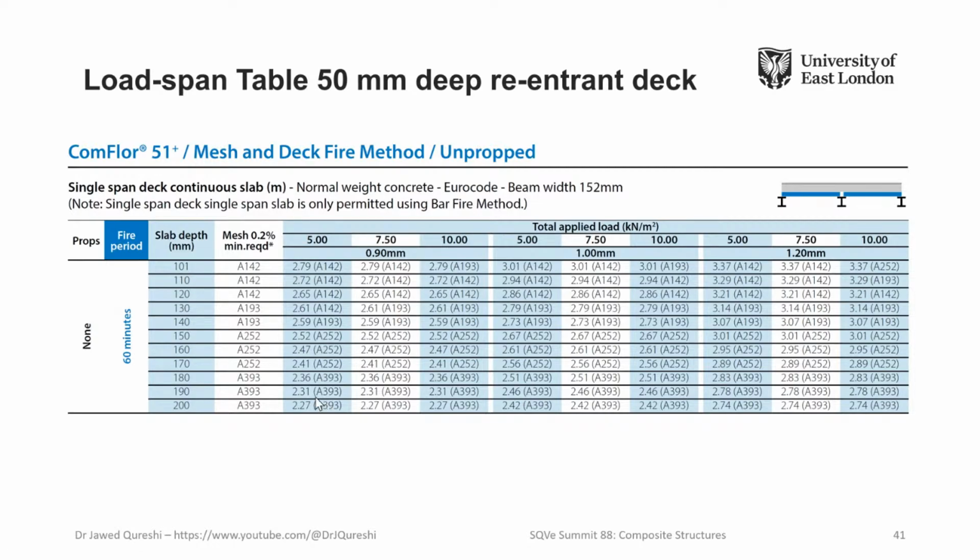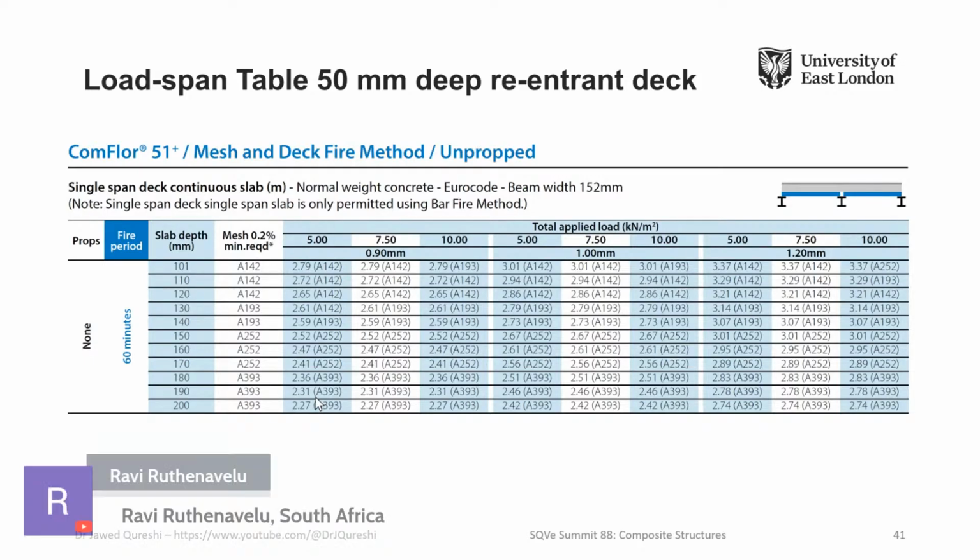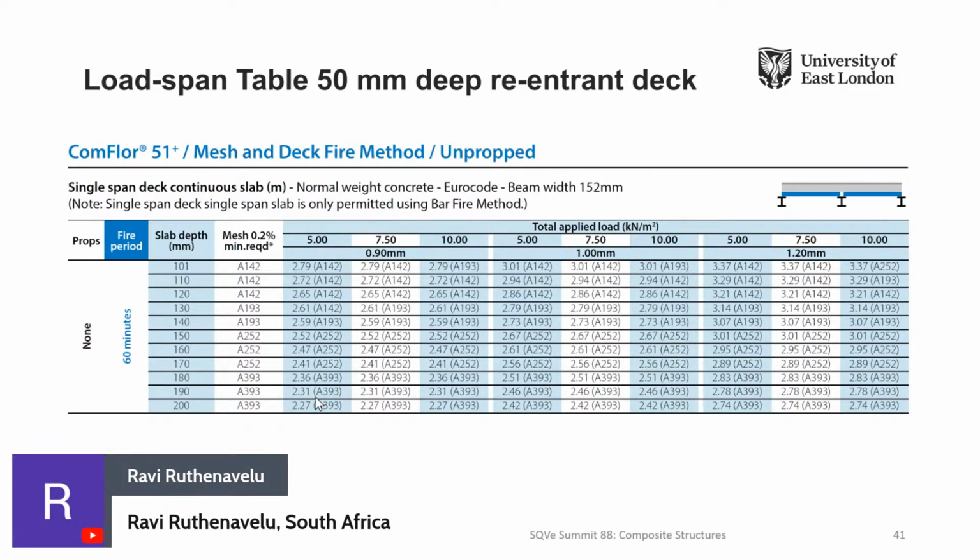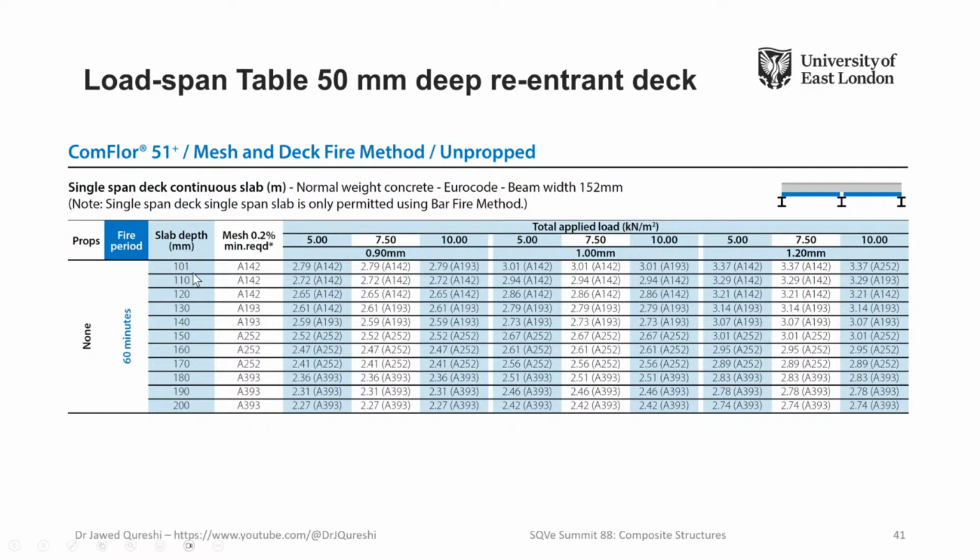Unless you have particular requirements for vibration of these floors, which should be checked, by all means go with a simple one. Go with the smallest one. In that way, you can justify that using this sheeting, this height of the slab, and this mesh reinforcement, you can use this sheeting without performing detailed calculations.